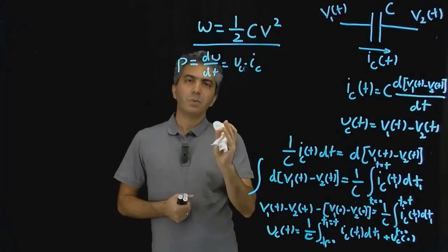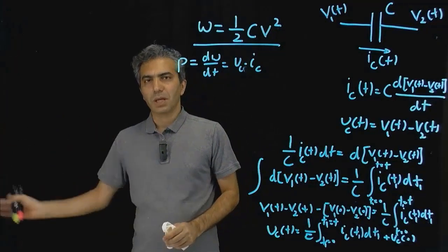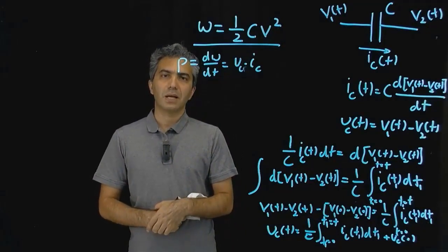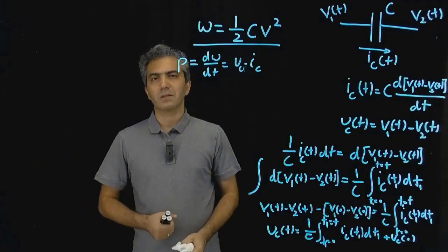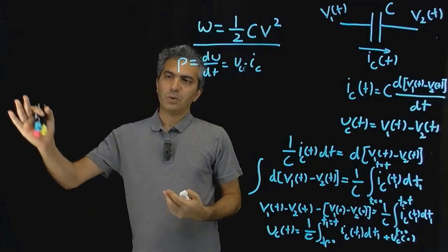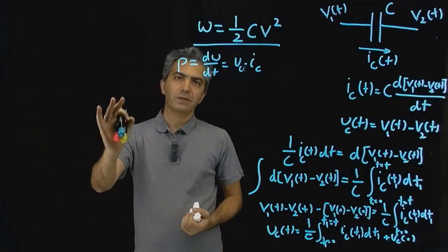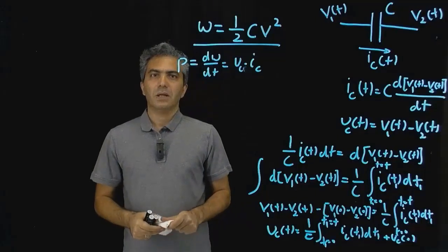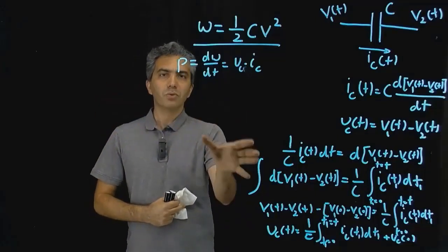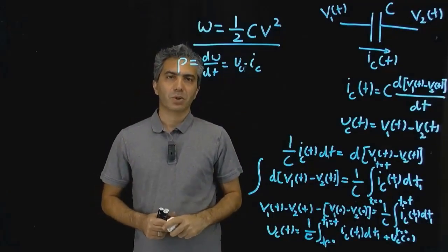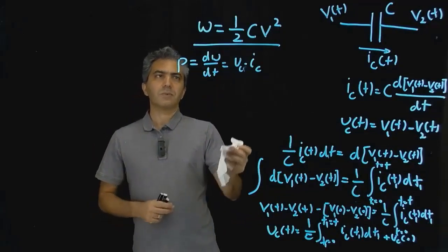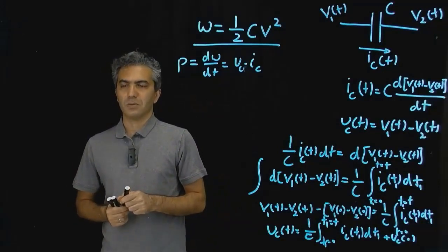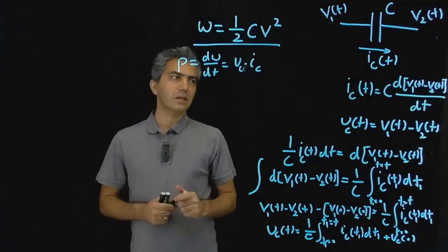So if you recall, once we defined resistors back closer to the beginning of this series of lectures, immediately after that we discussed resistive circuits, and we mentioned that once you connect networks of resistors to each other, you can calculate an equivalent for those networks, so that you can represent the same functionality using only one resistor. We came up with rules that would quickly simplify resistive networks. We can replicate the same thing with capacitors, and sometimes those come quite handy. So I'm going to show you how you can do that with capacitors in parallel and capacitors in series.